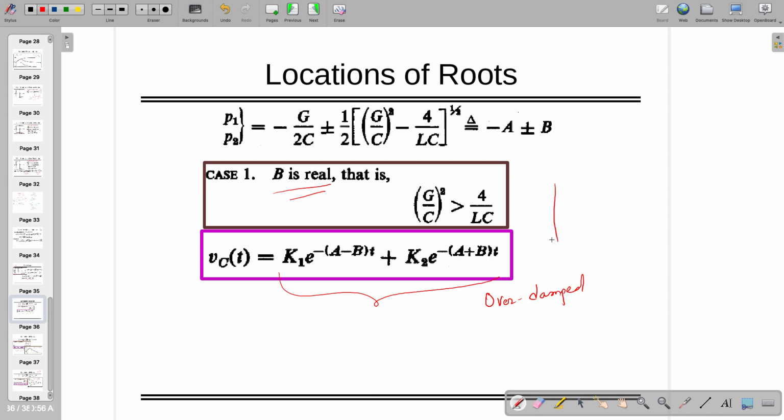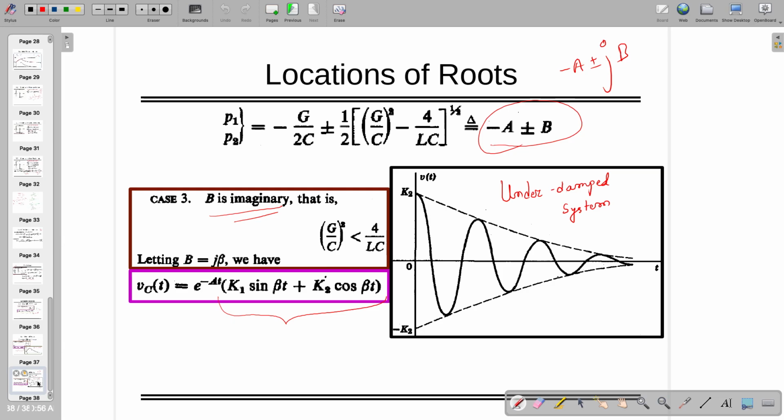The answer will always be like this, right? And this is always a stable system, the first one. You need to look at where the poles or the roots are available. If the first pole is inside UGBW and the others are outside UGBW, the system is stable. You will not see any kind of ringing. No problem. Right?